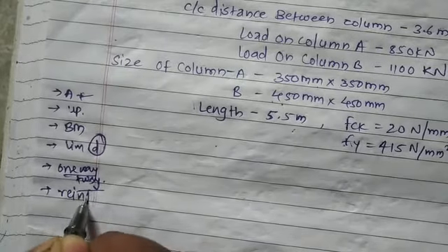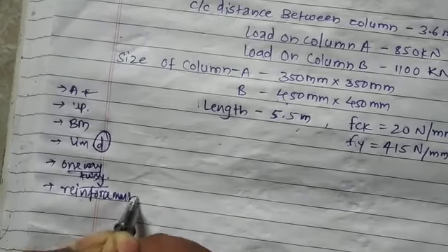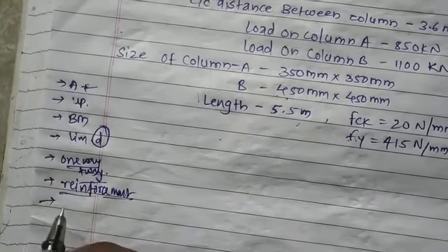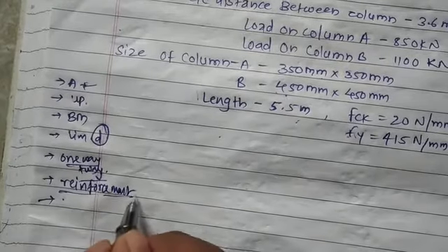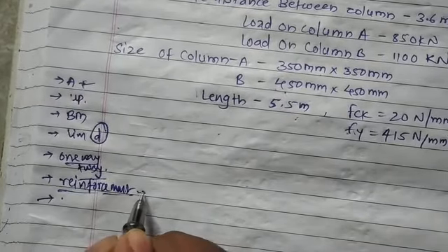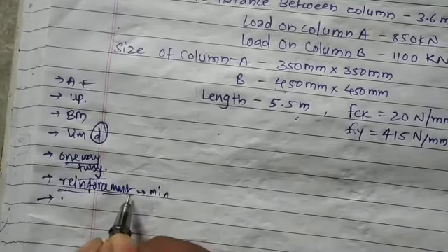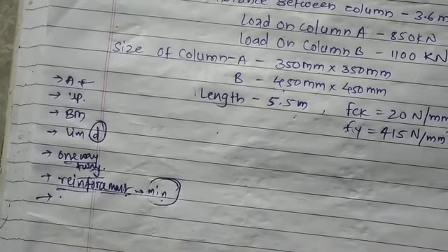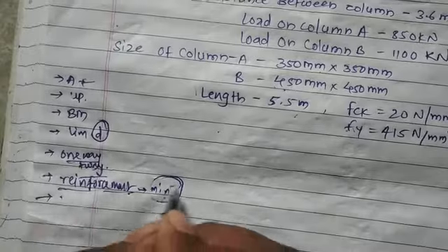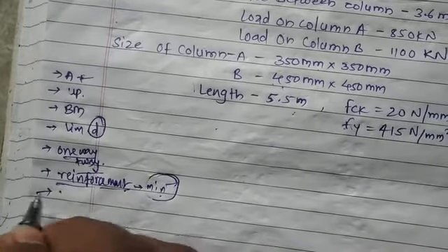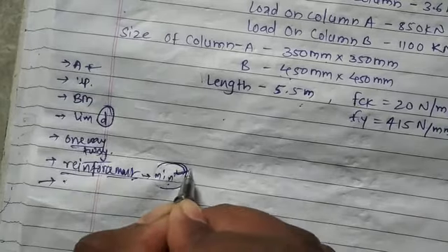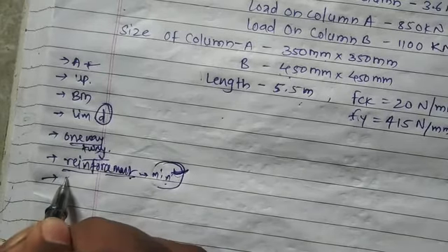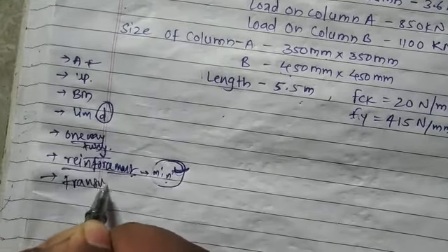So we'll provide reinforcement according to the moment we have got at that point. We'll also check this reinforcement whether it is greater than the minimum reinforcement or not. If it is not greater than minimum reinforcement, then we'll provide the minimum as reinforcement at any section. So after providing this longitudinal reinforcement, we'll design all the details like spacing, the shear reinforcement for main reinforcement, and we'll also design transverse reinforcement.